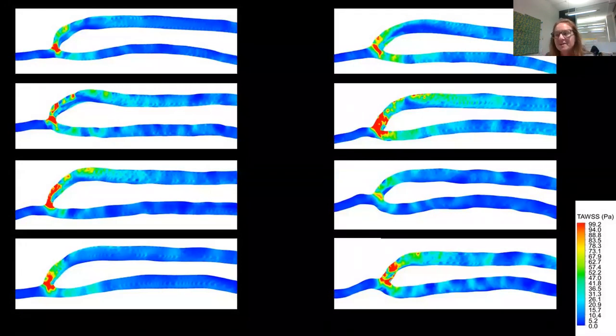But with our model being the size it is, there's no way we can do that. So we do the same with our LDA system. We build whatever thickness of PDMS or acrylic that we need in front of the calibration, and then we calibrate it, and then we put the model back into the same position.